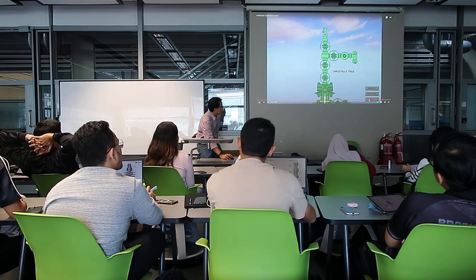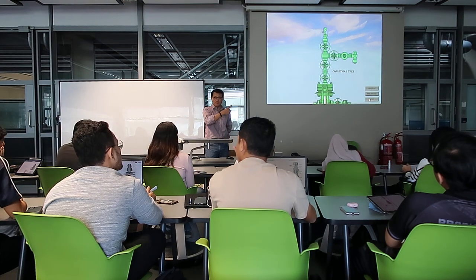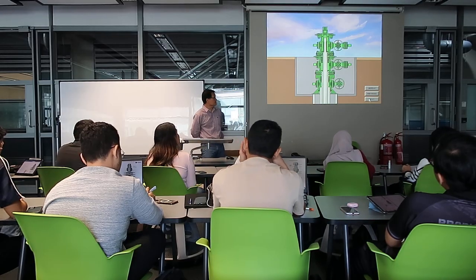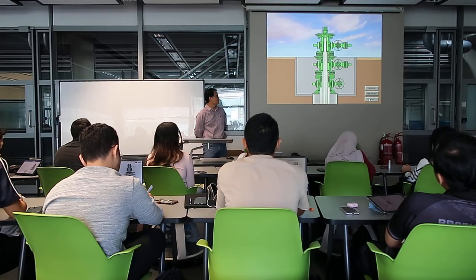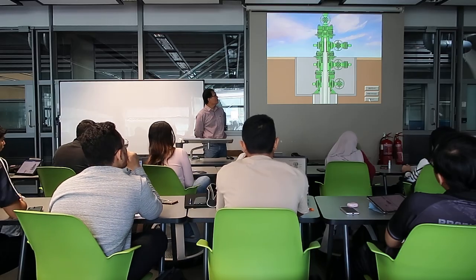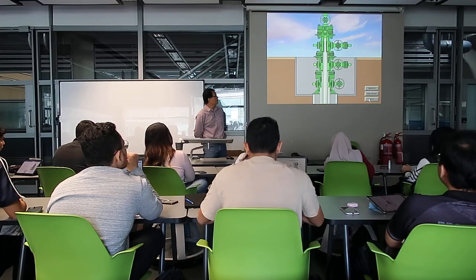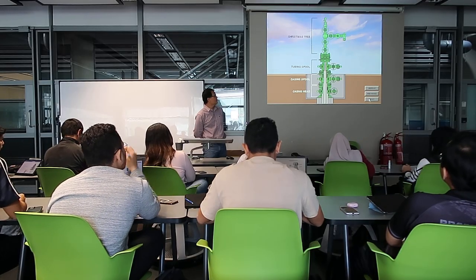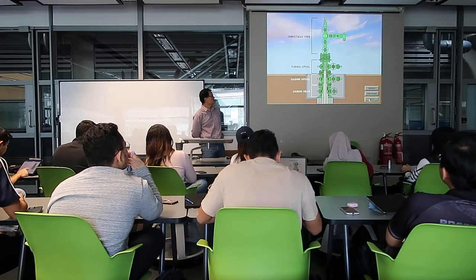It will shut down the well in an emergency and prevent damage of the equipment downstream. To install the Christmas tree, determine the direction the Christmas tree should be installed, pick it up, level it, and lower it over the extended neck of the mandrel tubing hanger. The Christmas tree is nipped up to the tubing spool, and the connections and seals are tested. The well is now ready for production testing.